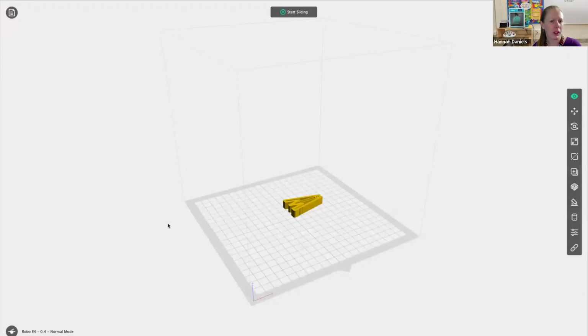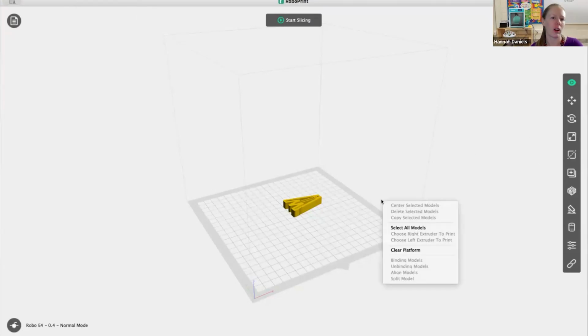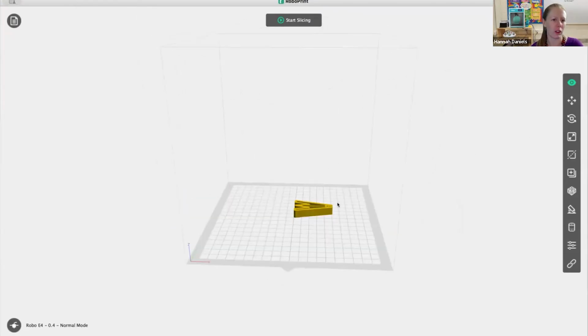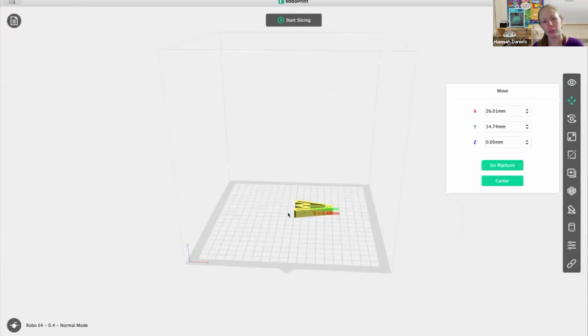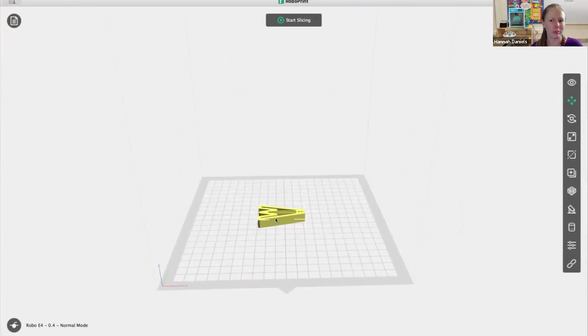Yeah, so I'll take the ideal minimum thickness. I would say 2 millimeters is my general minimum. If you're doing something like a lithophane, you can go thinner than that as long as there is enough support around it. But for a lot of designs like keychains and stuff, I do 2 or 3 millimeter bases, and then you can have some more detail on top of it. But often you don't want to go too much thinner than that.